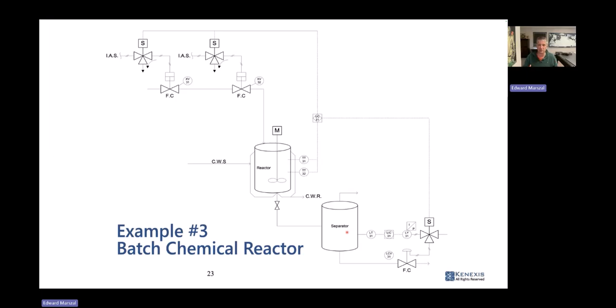It's going to put us into a known state, but closure of this valve, and probably you're going to set this controller to 0% and manual. We're making life easy for the operator. We're taking work out of the operator's hands, setting the process into a known state so that it's easy to restart. But this action is not safety critical. It's not required to prevent the runaway reaction, so don't include it in your safety function.